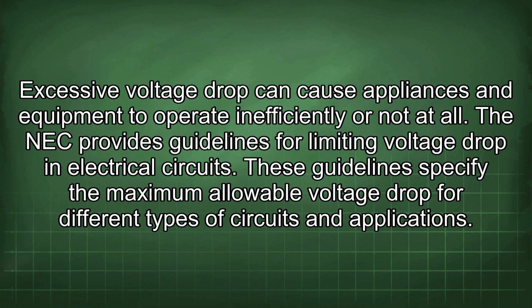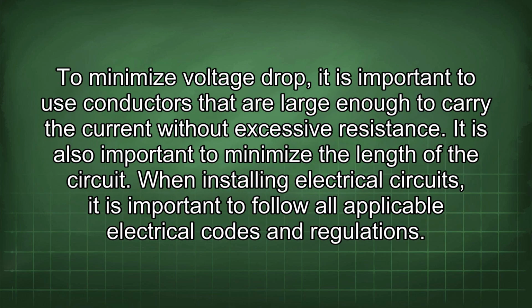The NEC provides guidelines for limiting voltage drop in electrical circuits. These guidelines specify the maximum allowable voltage drop for different types of circuits and applications. To minimize voltage drop, it is important to use conductors that are large enough to carry the current without excessive resistance. It is also important to minimize the length of the circuit.